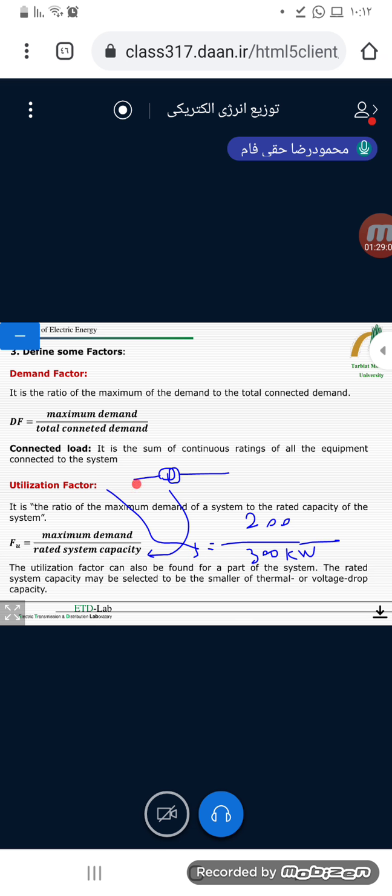For example, in Iran, the utilization factor in transformers is between 0.30 and 0.7. If the utilization factor is close to 1, the transformer does not have any reserve margin, and if it reaches the lowest, it shows the placement of the transformer is not in a good situation.